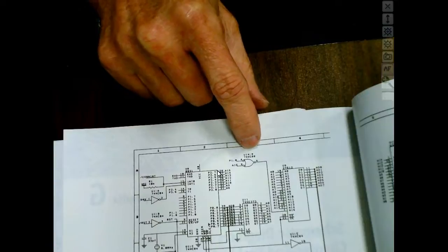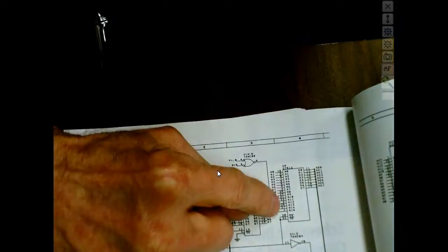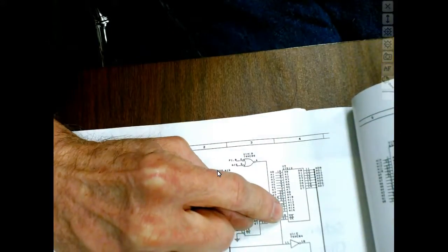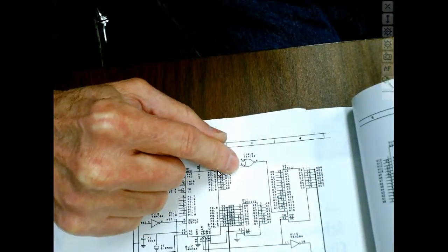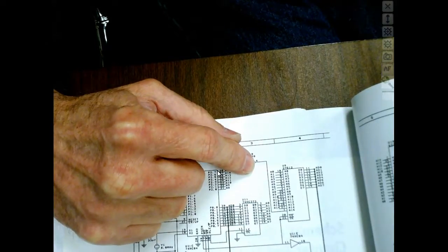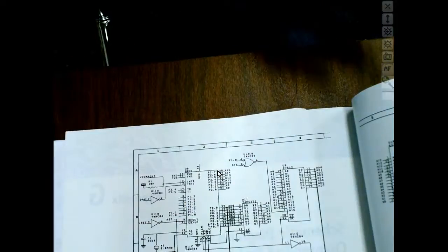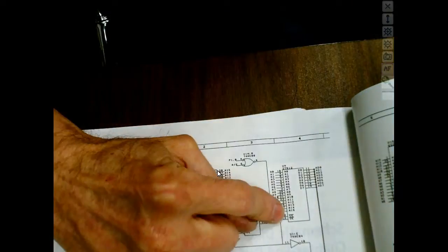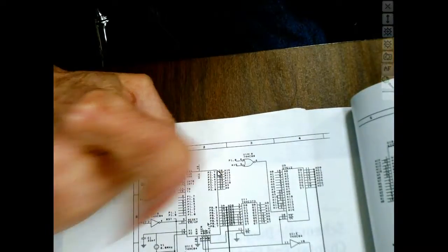This is an AND gate, but they got it drawn as a negative NOR, because what this guy right here is looking for is not a high, it's looking for a low. That's what it needs. And what does this say? Well, this says any low will give me a low. You understand? If this was drawn as an AND gate, then I would have to figure out what this guy's looking for, right? But it's drawn that way.